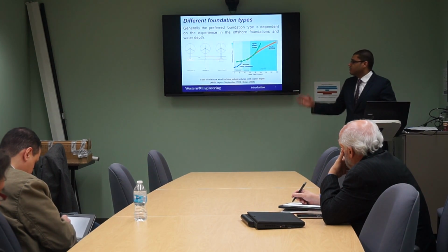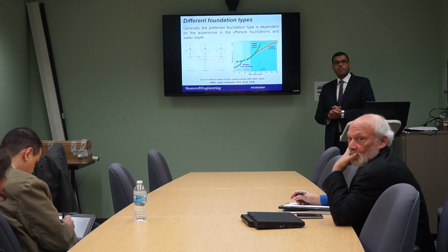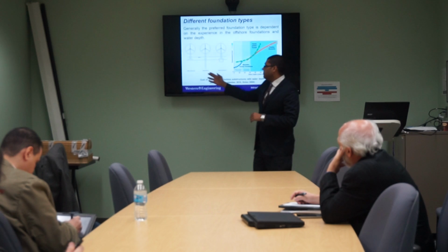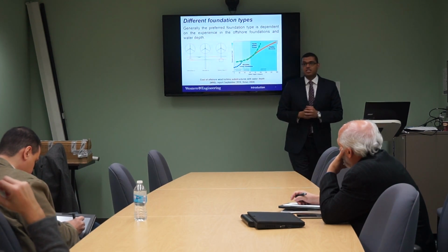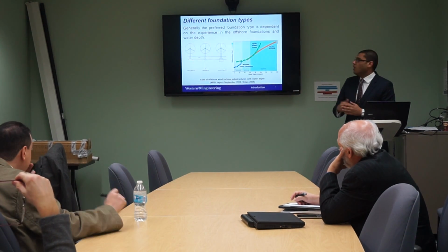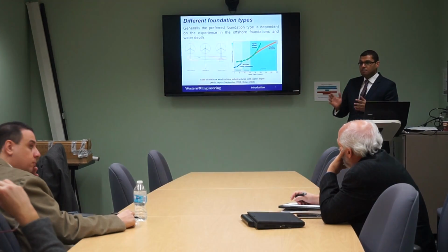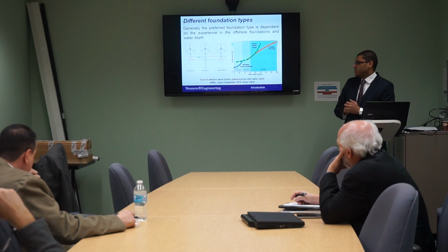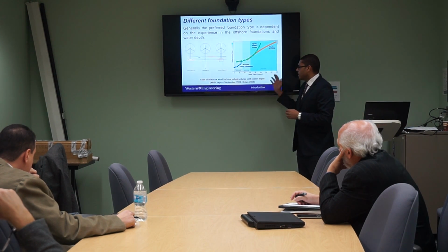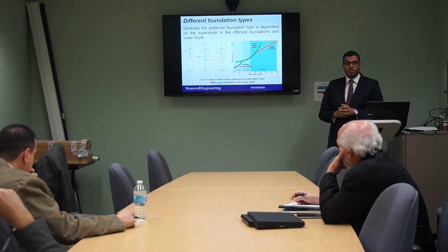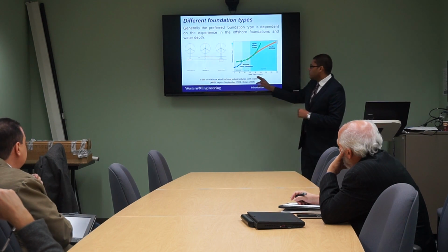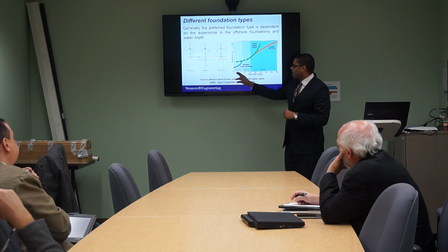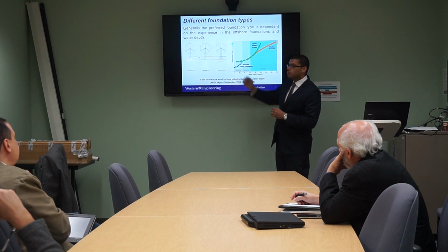We can see here different offshore foundation types, starting from gravity-based, monopile, suction caisson. This depends on our experience from offshore foundations, which came mainly from the oil sector, which is different from the wind energy sector. We can see here this figure from NREL, National Renewable Energy Laboratory, where it shows the relation between water depth in meters and substructure cost. We can see here that with increasing water depth, substructure cost will increase.